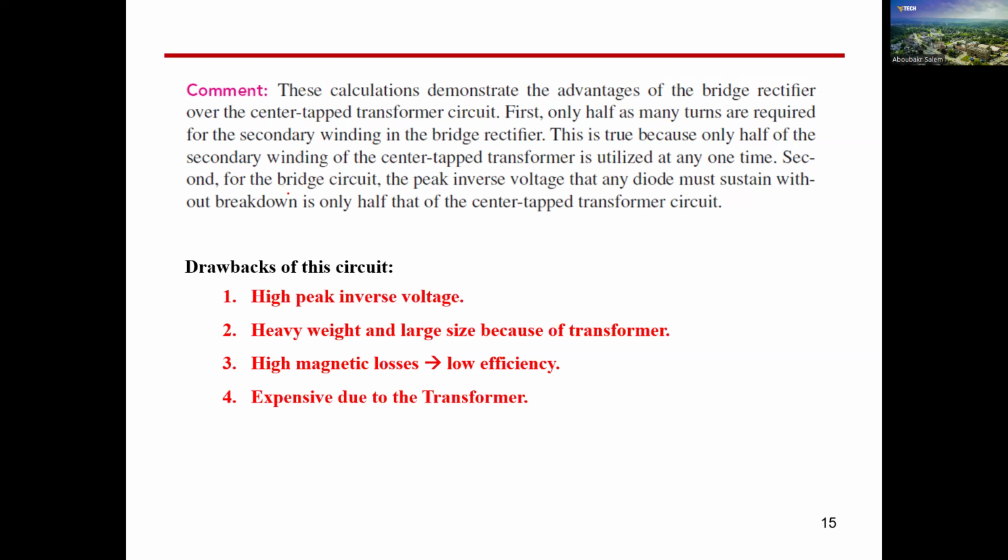For that, the center tap transformer is relatively high priced. The second thing is that in the bridge circuit, the peak inverse voltage that any diode must sustain without breakdown is only half that of the center tap. So we can conclude these in 4 points, as you can see here.